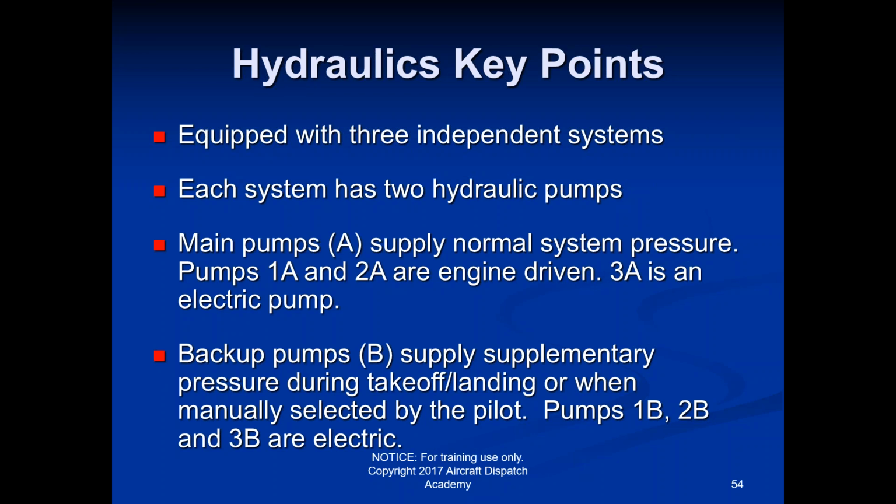So if you had an engine failure on your left engine, then that is going to shut down hydraulic System 1. This is kind of going back to the redundancy thing again. System 2 is running from the right engine, and as long as that engine is working, that system is working. But if that engine were to fail as well, then System 2 would go down. Now, when you say System 2 would go down, it just means that pumps 1A and 2A go down, because those are engine-driven pumps. So the engine has to be working in order for those pumps to be working.